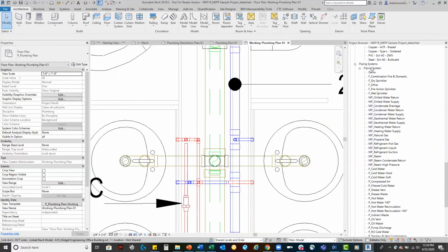But then if we look at the piping systems, you'll notice that we've created quite a bit, okay? We did leverage the fire protection stuff for fire protection stuff, even though we know it doesn't do analytics, okay? Reason being is that there's a very small number of people doing fire protection design in Revit. If you have some interest in doing fire protection design in Revit and you want to propagate flow, you can leverage the hydronic supply or hydronic return system classifications to do that for you.